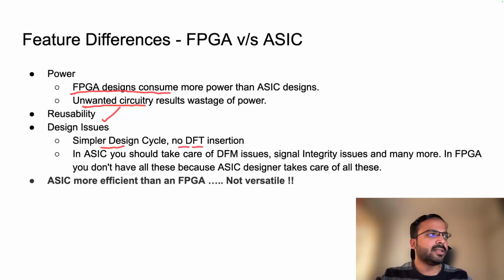There is no DFT insertion. DFT is design for testability, your boundary scans, your JTAG scans, and all that, which is used for post-silicon verification. It is required to give the chip testability, so you can test whether there is some manufacturing defect and all that. Those are inserted in ASIC designs, but not in FPGA. Hence, the design issues are expected to be fewer in FPGA as compared to ASICs.